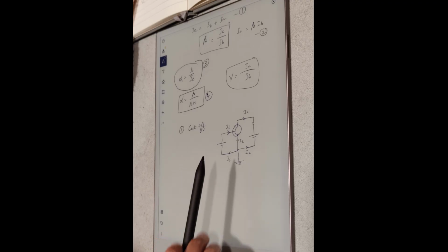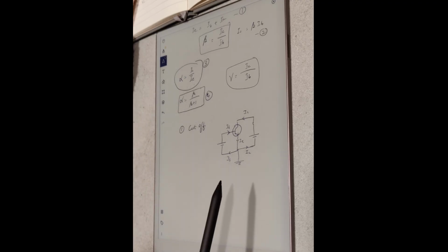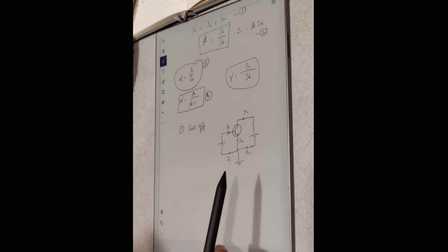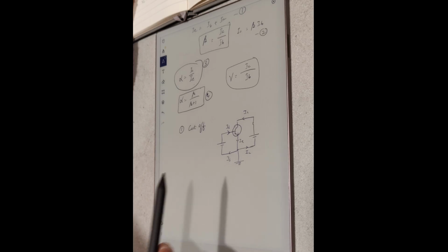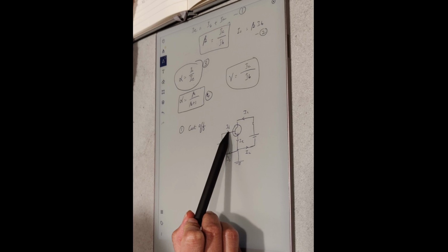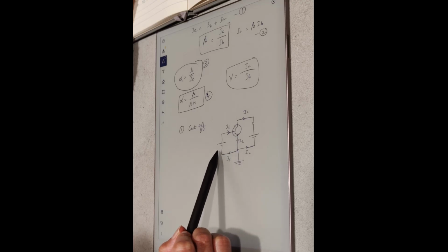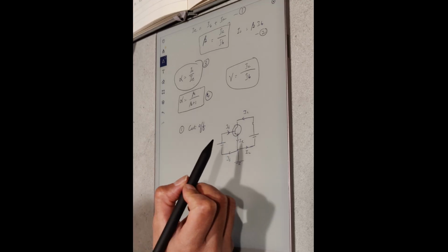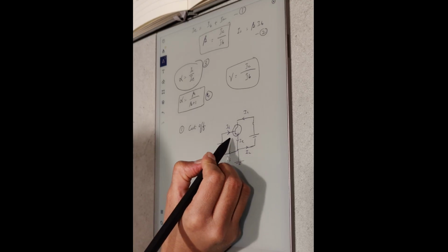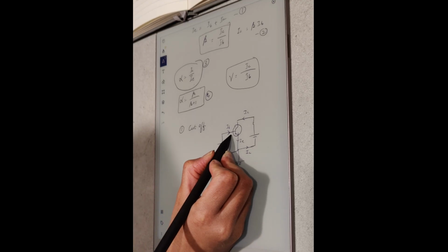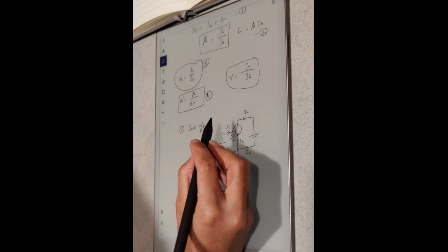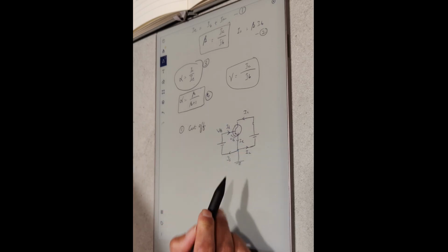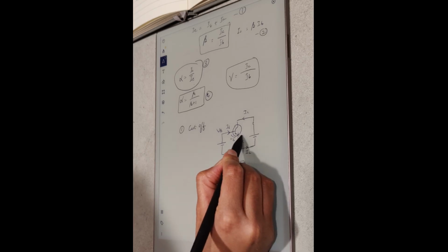Now remember, when we were doing the analysis at the electron level, we said there is a potential barrier of 0.7 volt, especially for silicon-based semiconductors at the junction. So for the current to flow from this side to this side for this input circuit, it has to be forward bias. And because of the junction, there is going to be a potential drop of 0.7 volts. So let's call the voltage here VB, and the voltage at this VE.